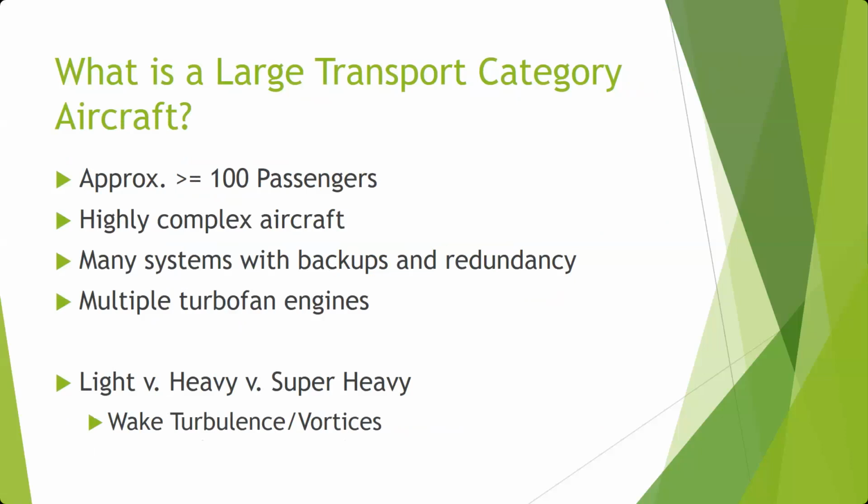Except there are a few. The big notable one is the Boeing 757, which is a single aisle aircraft, but it's referred to as heavy. Particularly the older versions that didn't have winglets, they gave off massive wingtip vortices and have flipped quite a few commuter and personal airplanes that tried to take off too close behind them. And so they were given that designation.